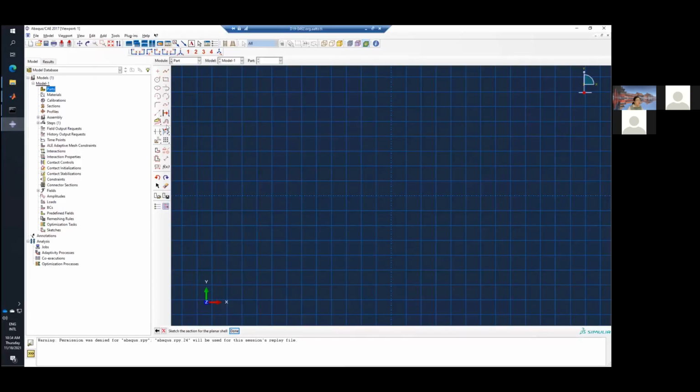Therefore, if you go back to your Abaqus, you first click this rectangle tool, and your starting point will be the origin point 0, 0, and click it. Then if you move your mouse, you will see a predefined rectangle will show like this. Then you find this point, not this one, this one. So it should be with a width of 3 and length of 5. You can see the position of your mouse will show on the left bottom or left top. Then you click this point, you will see the rectangle become yellow. Then you have already generated this part.